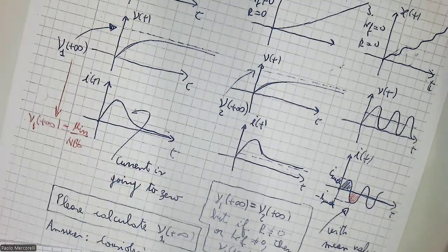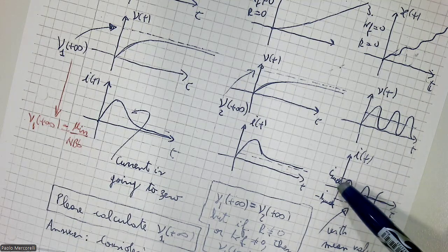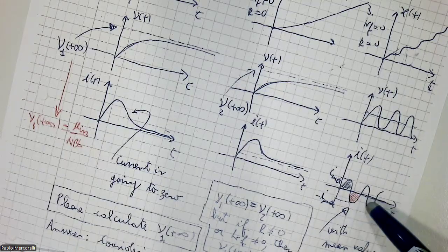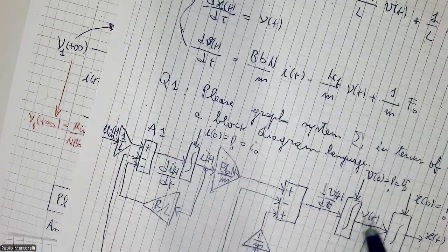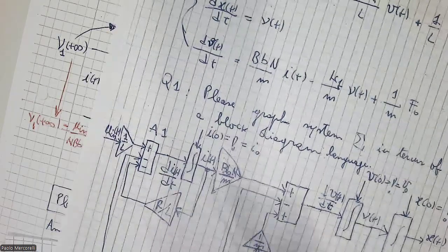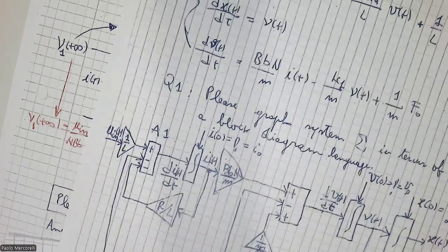Here's the position, which is going ahead, but with these oscillations. Why the current nevertheless is positive, is negative, is positive, is negative? Yeah, why? The reason is the energy from electrical goes in mechanical, and from mechanical coming back totally as an electrical. We don't have losses.